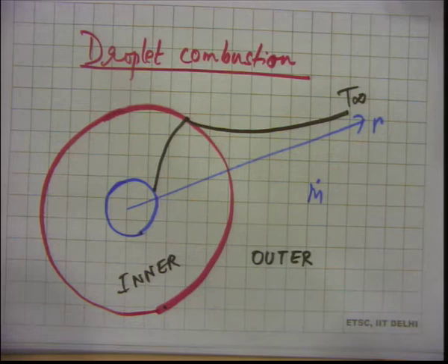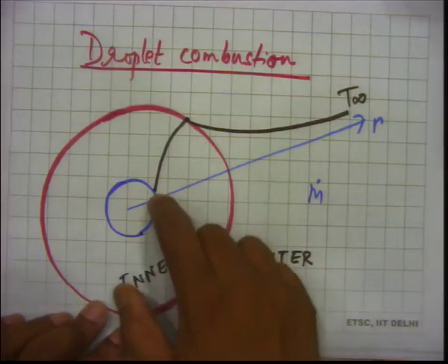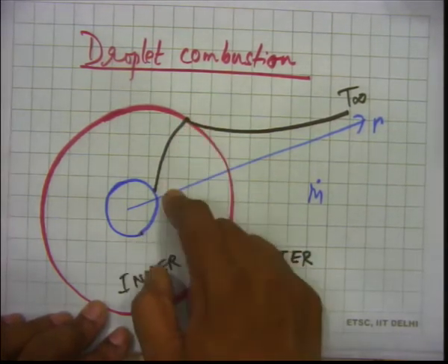Now this evaporation of the droplet, the liquid fuel is getting evaporated in the presence of combustion. Okay. So it's going to be more complicated, and we will have to bring in the fuel species equation and oxidizer species equation and energy conservation equation to solve these together to actually know which one is going to be this profile.